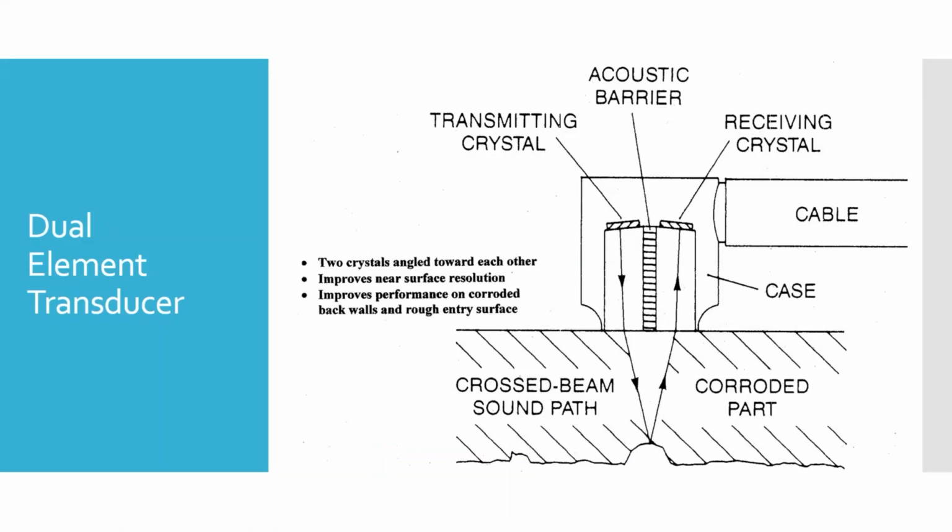The disadvantage is you do have to take into account that there is still a certain amount of refraction taking place, and so the probes have to be matched to the material that you're using them with. A standard probe has a single driver pickup element, a piezo element, performing transmission and receiving on the same crystal, and since it's going straight down and straight back up, you don't get any refraction.